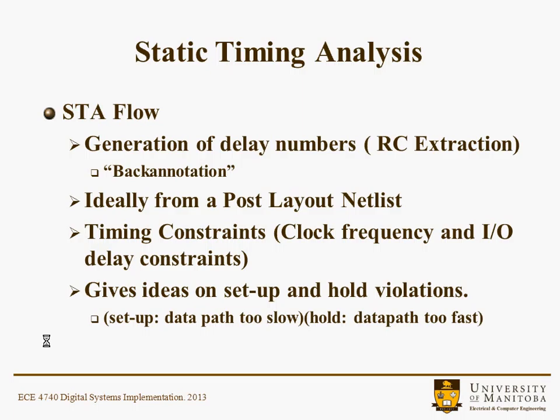The setup is where the data path is too slow. The hold is where the data path is too fast. And then there's a number of circuit design techniques that you can use to mitigate those problems.